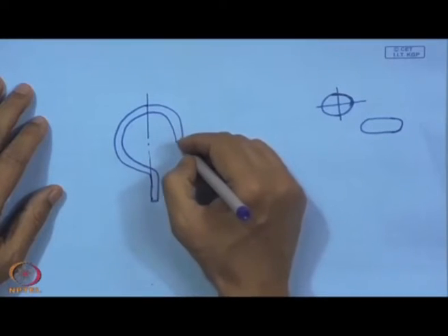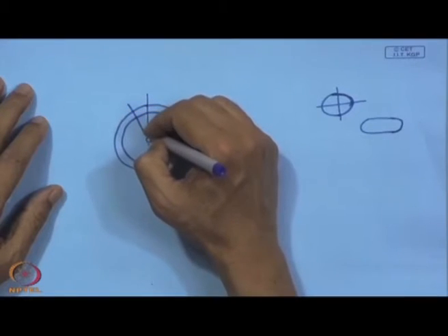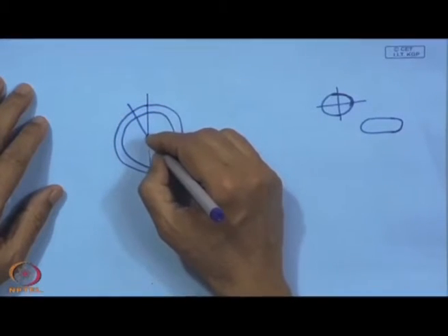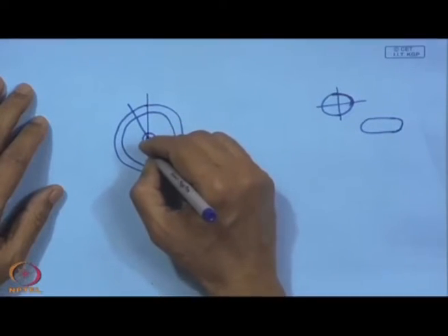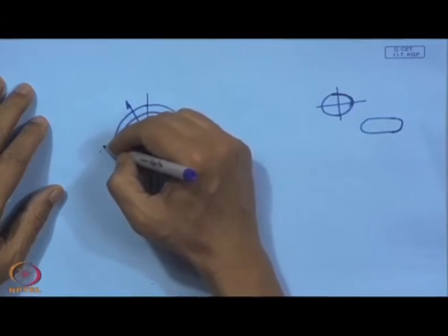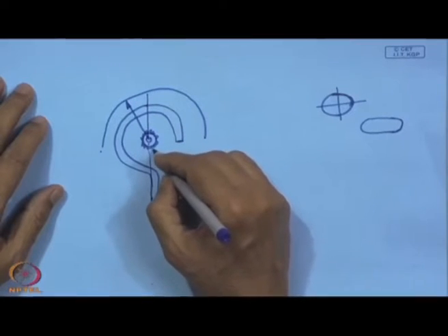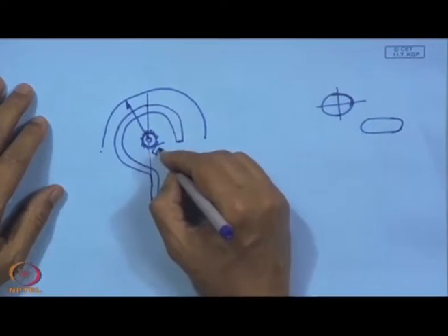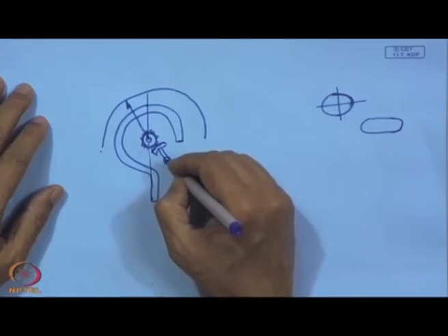So, this is the tube, and at the end, centrally, we have one needle, and this needle is fixed with one pinion, which is nothing but a toothed wheel. Here we have the pointer, and it can work over a scale. This will be in mesh with one sector gear like this, which also has teeth, and there we have one extension of this lever, and here we have a pivot.